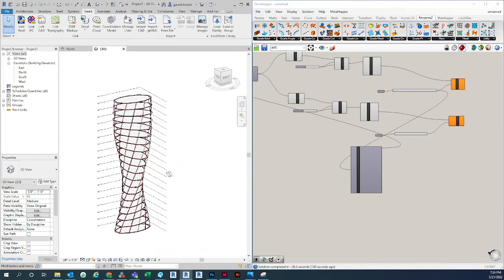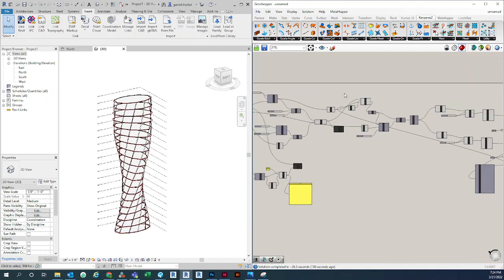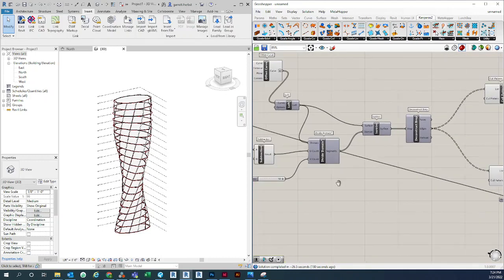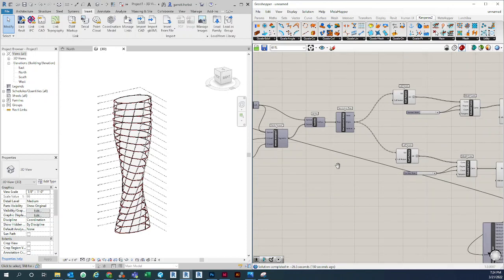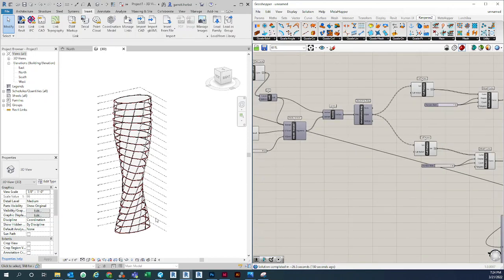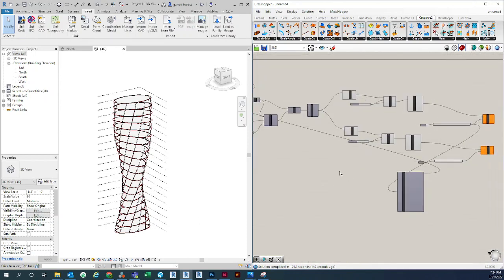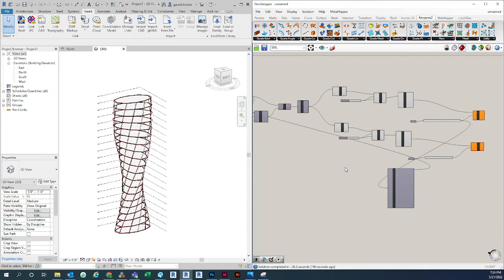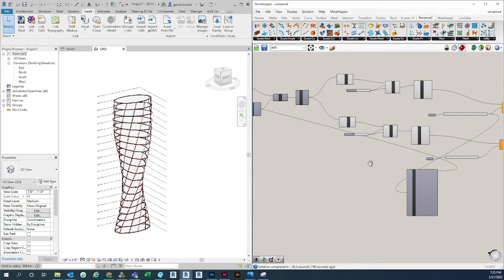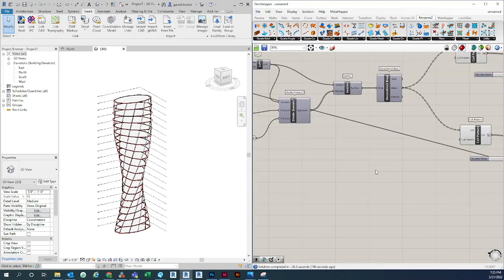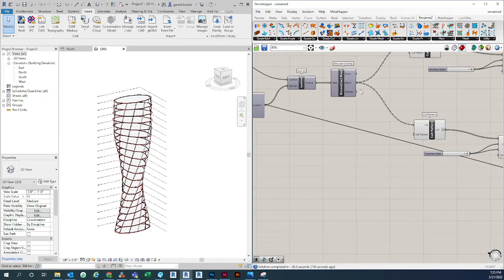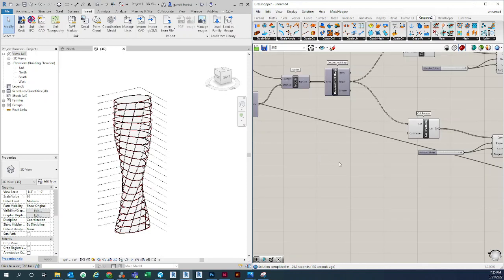So now you could do similar to what we had done before with the divide surface, creating those square panelized surfaces with a triangulated one. But there's a simpler option, at least with what we have currently created, that we can do using the vertices of the deconstructed BREP.